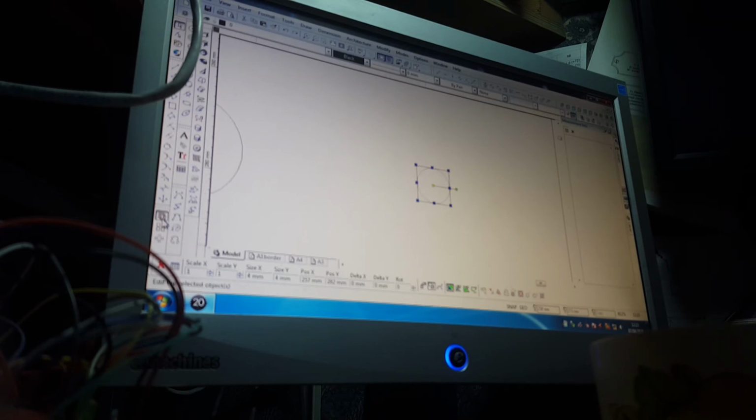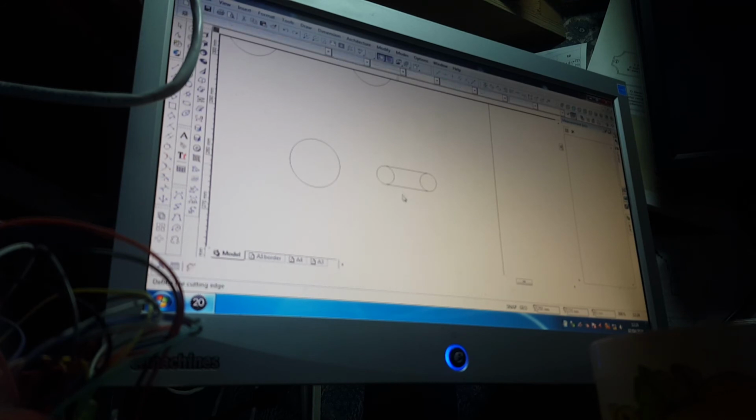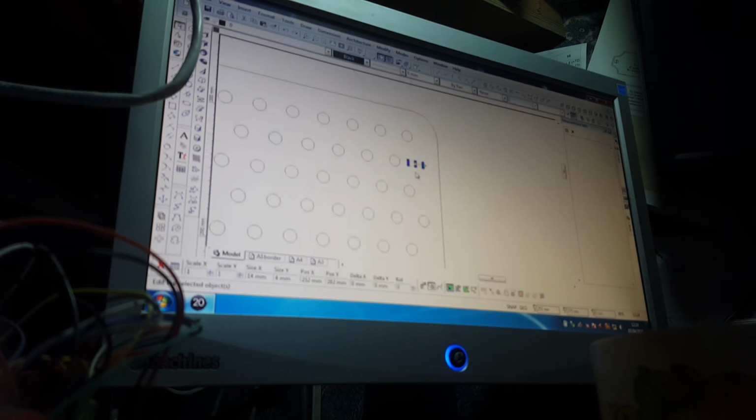So I'm going to use the old linear copy. I'm going to copy it minus 10, just 2 sets, and I'm then going to pick up the line tool, but tangent to 2 arcs. Snap there, there, there, there. Trim tool, multiple edges, trim that out. Polyline tool, auto joining, select. I've got a nice slot.